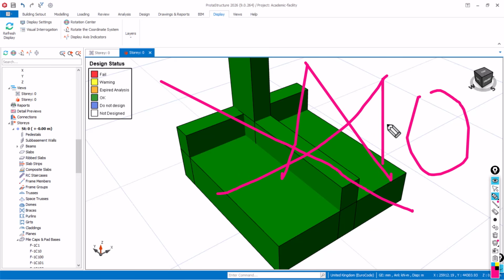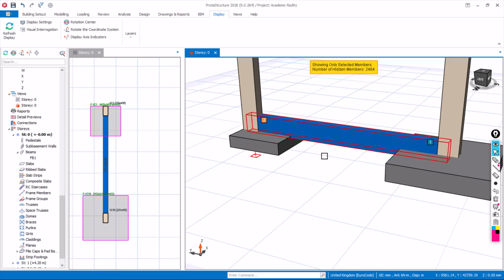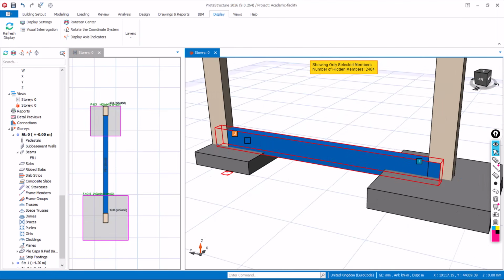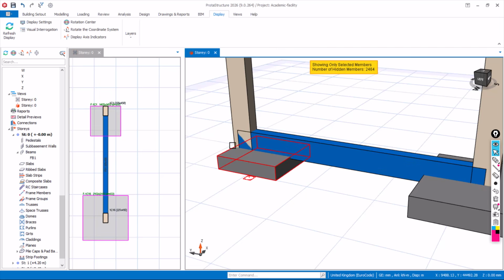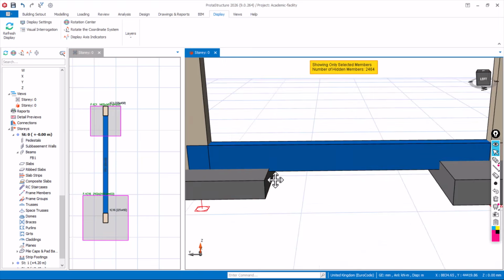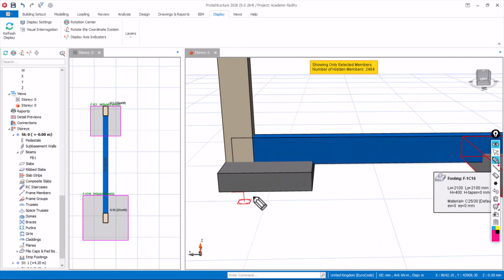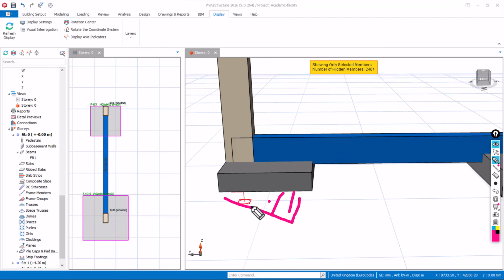Okay, that is fine. So the real engineering way is to model it directly as a strap beam. So at this place now, what you have done is stabilize the soil pressure that was triangular around this footing, as it was like this before, to now being uniform. Okay, you can see something like this. So the soil pressure now becomes uniform on this footing.